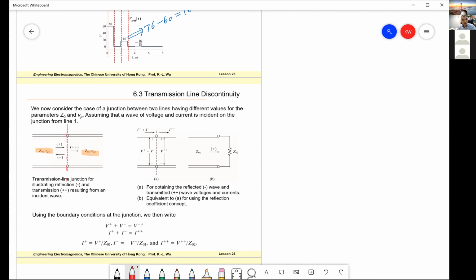This looks like the scenario when a plane wave hits a dielectric interface with another half of dielectric with different permittivity and permeability, right? And we know how to deal with that for a plane wave. But now we have the same thing, the difference being that the media change to a transmission line, characterized not by permeability, but by the intrinsic wave impedance, characteristic impedance, and wave velocity.